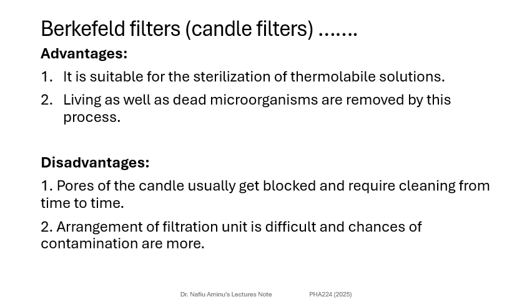It also has advantages and disadvantages. The advantages include that it is suitable for sterilization of thermolabile solutions. Those that cannot withstand heat, the candles can be utilized to process those solutions. Two, living as well as dead microorganisms can be removed by this. So both living and dead can be controlled using this kind of filter.